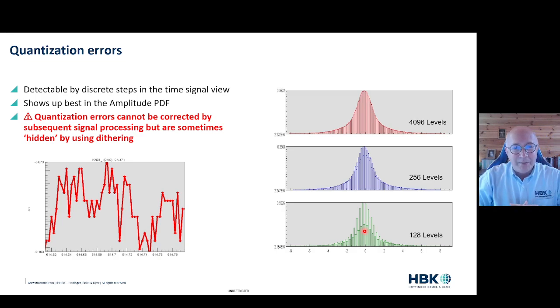Now, sometimes you'll read in books that there is a way of overcoming this called dithering. It's not overcoming it. What dithering is, is adding noise in at a low level such that when you redigitize it, it appears to be better than it was before. But it is just noise that you've added. So it's hiding the underlying effect. It's not actually a good way of trying to correct data. You can't correct it if you've not measured to the precision you want. You can merely smooth it over if you like.